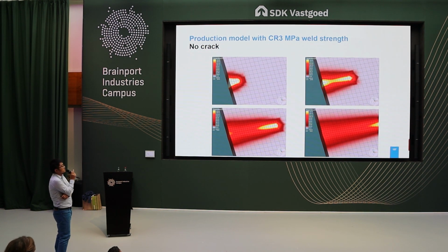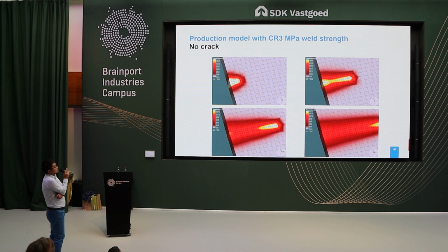I've chosen 4 time instances. The first one is when the weld just started, and the second one on the right-hand side is when the laser has moved a bit inside, but the starting edge is still molten. The third image is when the starting edge has cooled down to solid, and the fourth image is when the laser is moving further away into the sheet.